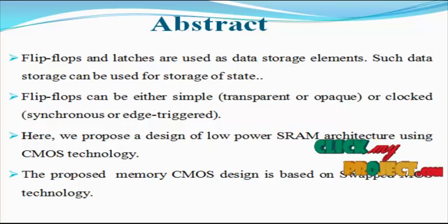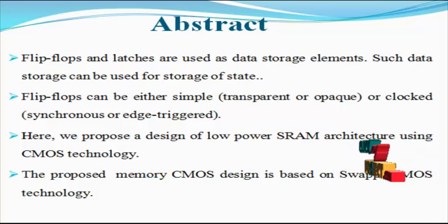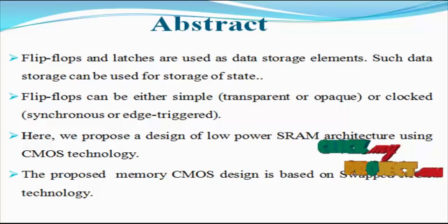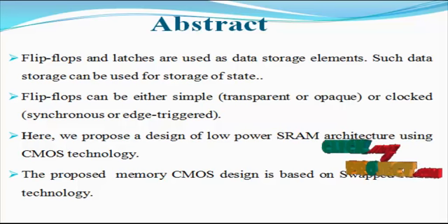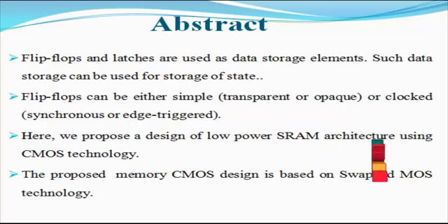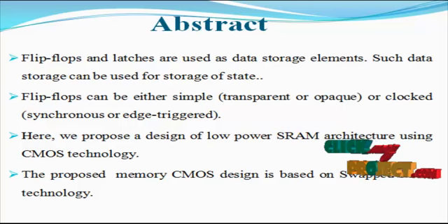The most commonly used SRAM type is the 6T SRAM, which offers better electronic performance in all aspects: speed, noise immunity and standby current. The smallest 6T SRAM cell fabricated to date has an area of 0.08 square micrometers and was developed in 20 nanometer technology.